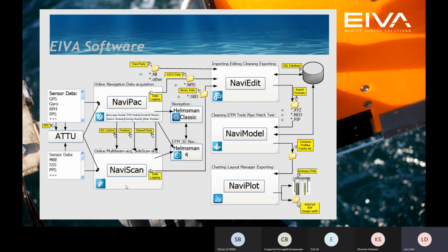When we talk about good data online, you can imagine that if you have your navigation, you are combining two transponder positions on the RV with a Doppler velocity log, then you get a really, really good online INS kind of position, and that's good online. But in post-processing, it would be a lot better to say, okay, I have my raw transponder position, I have my raw DVL data.